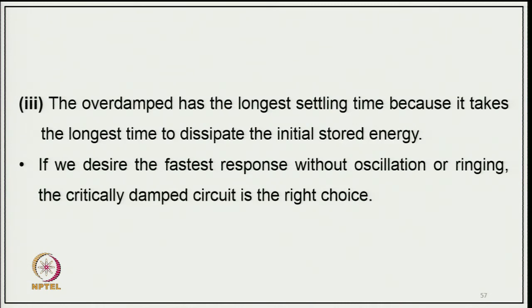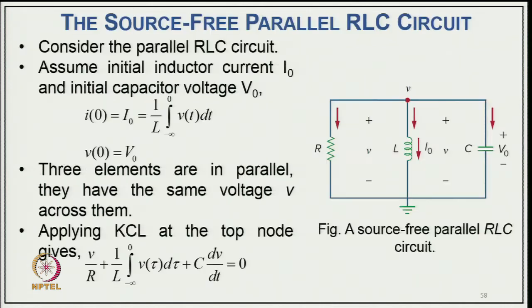So, overdamped has the longest settling time, because it takes the longest time to dissipate the initially stored energy, and if we desire the fastest response without oscillations or ringing, the critically damped circuit is the right choice.